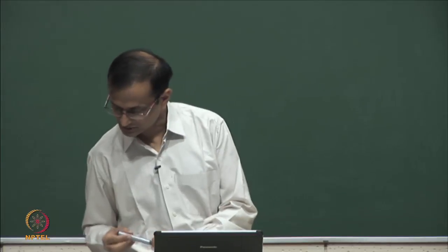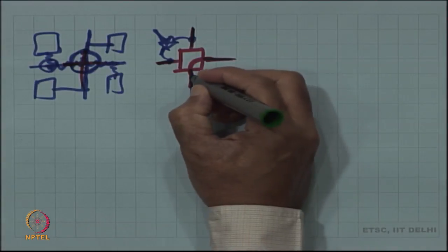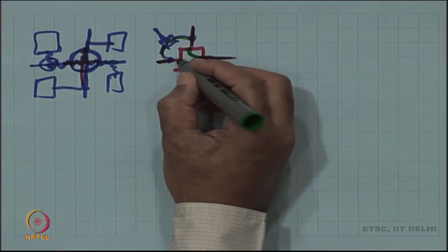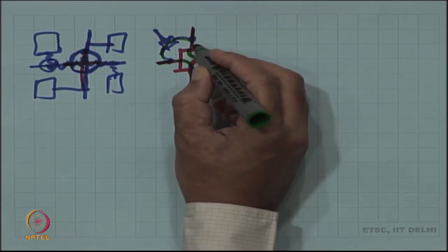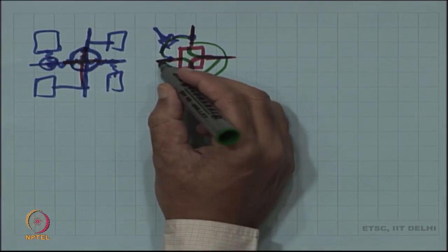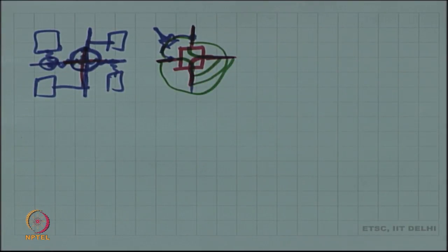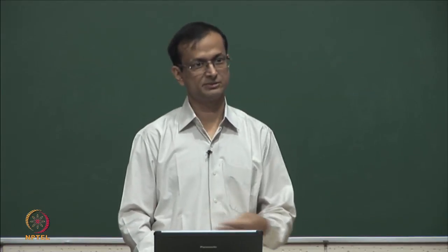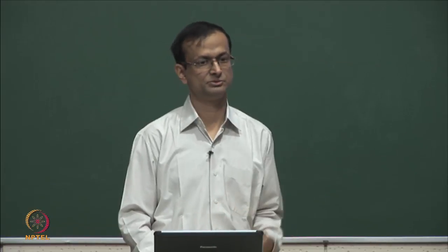There are 6 pairs here, right. This could be one pair, that could be one pair, this could be one pair, this could be one pair, that could be one pair, and this could be one pair. Each of these you might want to connect or might not want to connect. Okay. And so, it is essentially 6 transistors that you need and 6 bits that control each of the gates of the transistors. The programmable interconnect would be just that. For one bit, if it is a bus that is coming in of 4 bits or whatever, the same structure has to be repeated 4 times.